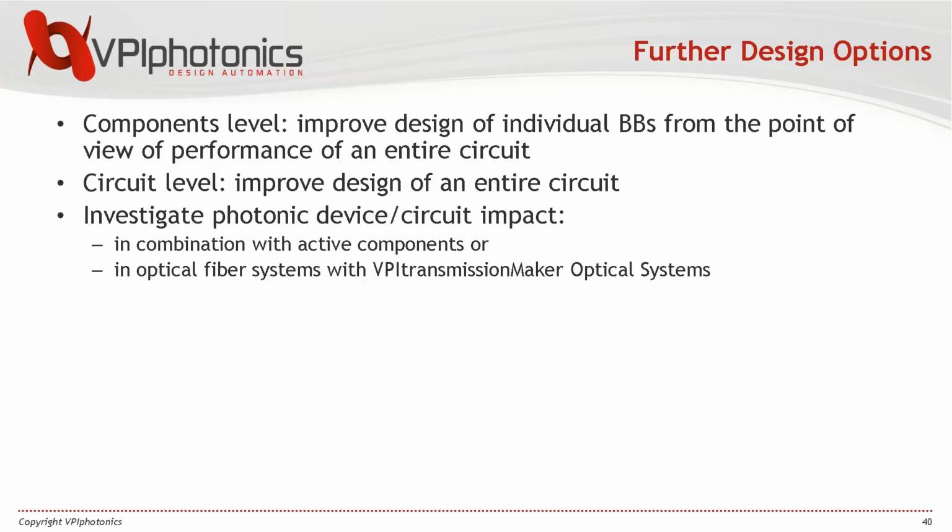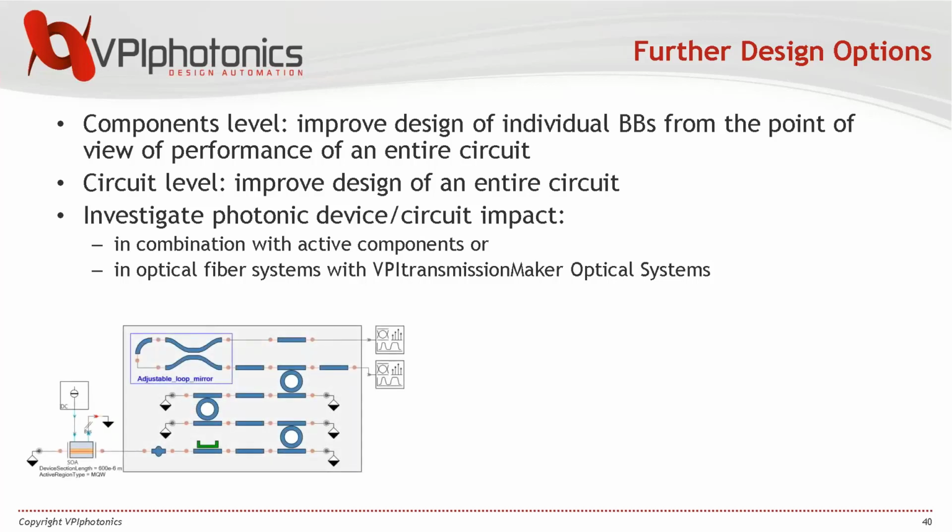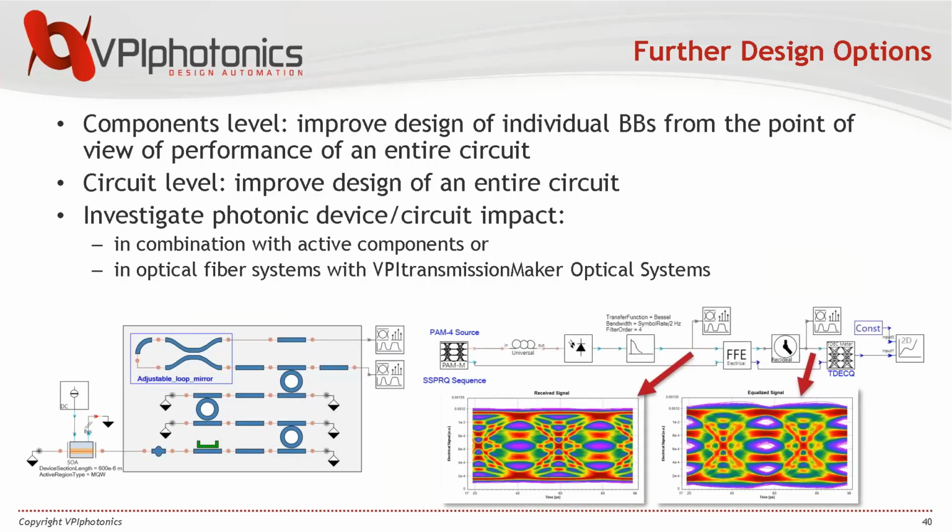And finally, you should remember that you designed it for some application. For example, if it is for active components and you should launch some light from an active component, a laser or SOA, you would probably need to simulate that, because if you have some reflections on the interface, most likely it will change the spectrum of your active component significantly. Or even go higher and perform system level simulations.